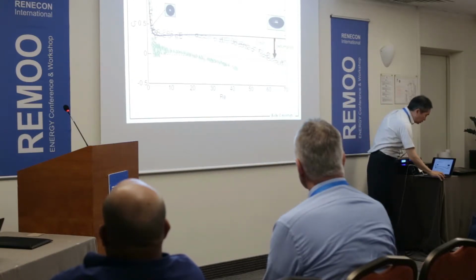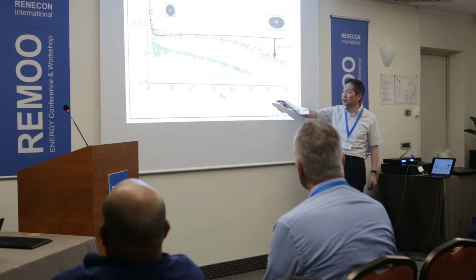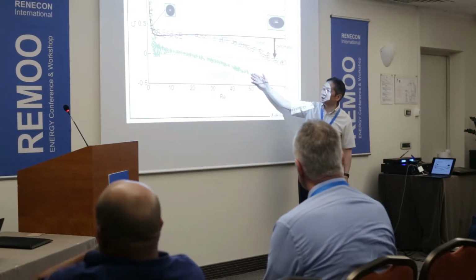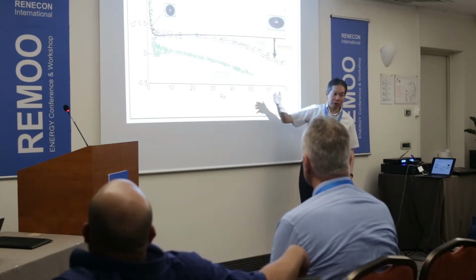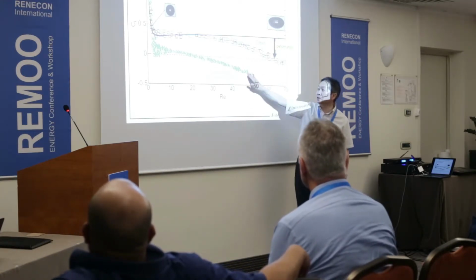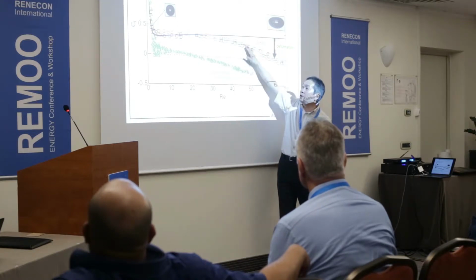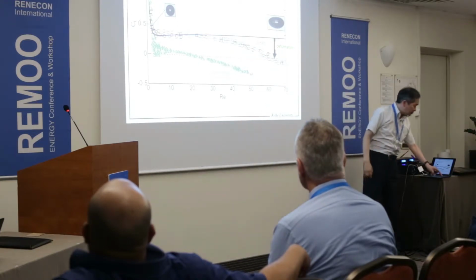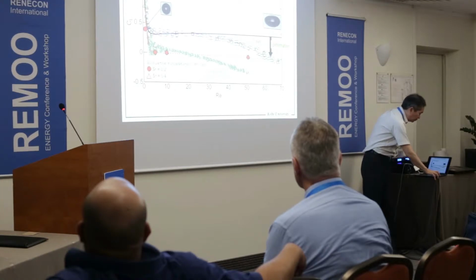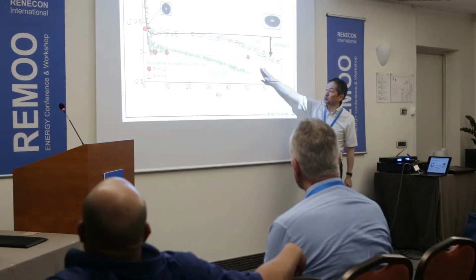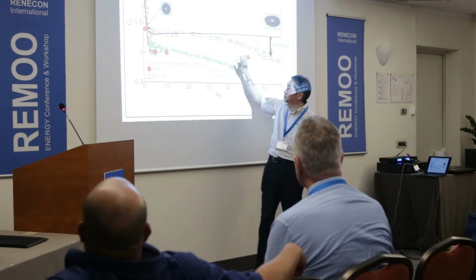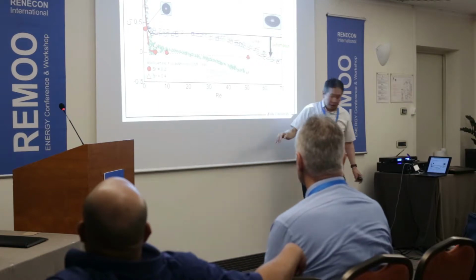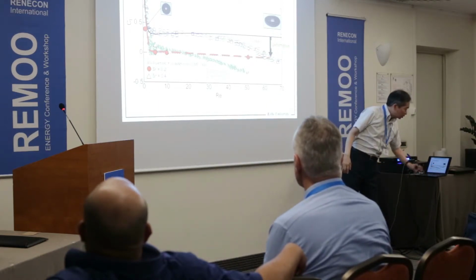And we also obtained data for the contaminated system. Here, this is the lift coefficient for bubbles contaminated with surfactant. And in this case, the value is very low compared with a clean bubble. And compared with a spherical particle, this is a numerical prediction obtained by Dr. Kurose and Professor Komori, and it goes straight in this way.